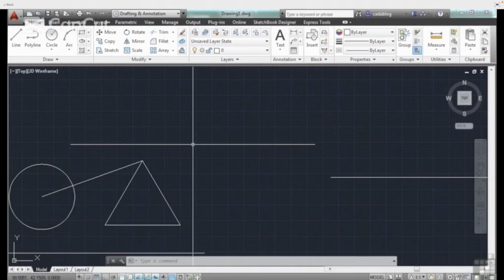Again, these tracking devices, the polar tracking and the O-snap tracking, we'll talk about them later on in more depth in a section. But the function keys turn on and off these certain tools that allow you to draw more accurately, or draw better even. Make sure to watch the video pertaining to each of these tools for more in-depth descriptions of them.